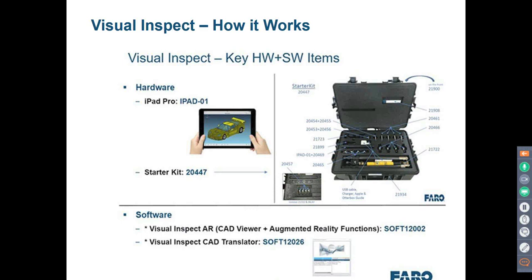You can use up to 16 markers to give you more freedom in moving around, but the camera always has to have 4 markers inside. That is real time. And then we have the possibility of using pre-taken pictures. These pictures can be done on the fly with an iPad camera, or we even have the opportunity to use higher resolution external cameras. And with the use of these pictures, you have the advantage that when you place this picture into your model, it's stored there for further reuse.